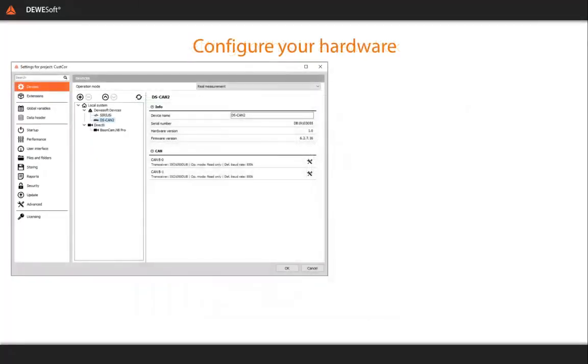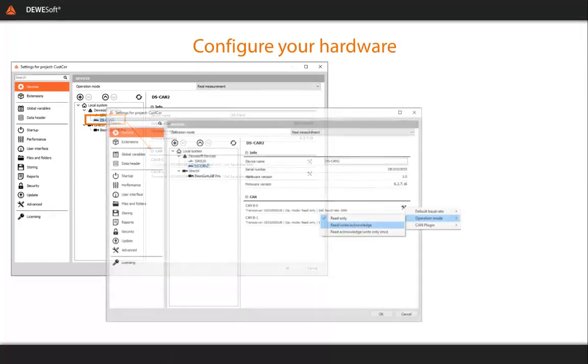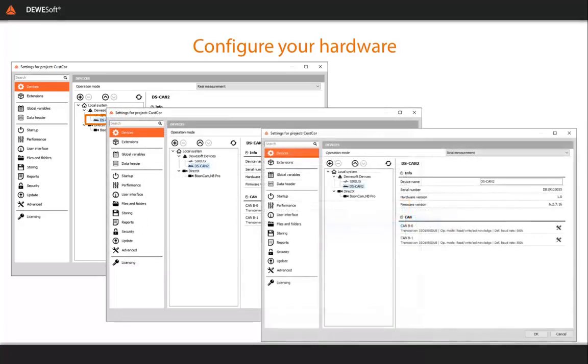So always start by making sure that you have your hardware configured correctly, and any extensions that you plan to use added and active. It's always a good idea to check that you're in an acknowledge mode for most automotive applications, and really important at this point, check that you have the required termination. Sorry, we only alluded to that earlier, but it is very important, and it's a 120 ohm resistor across CAN high and CAN low, and that's only if it's required.